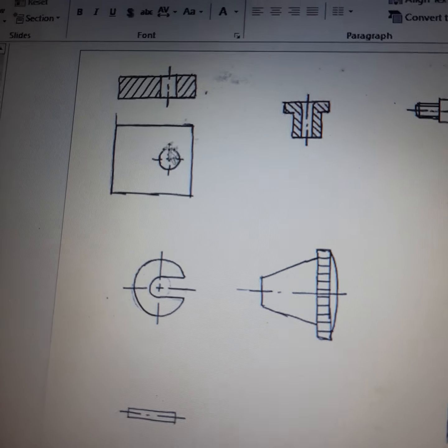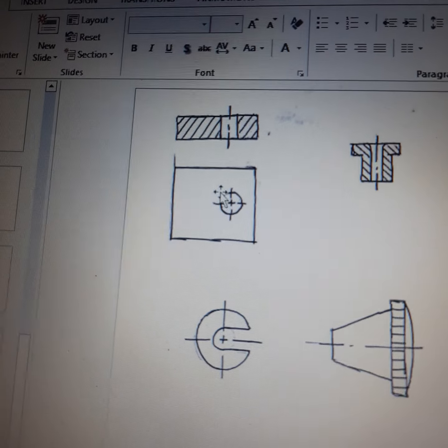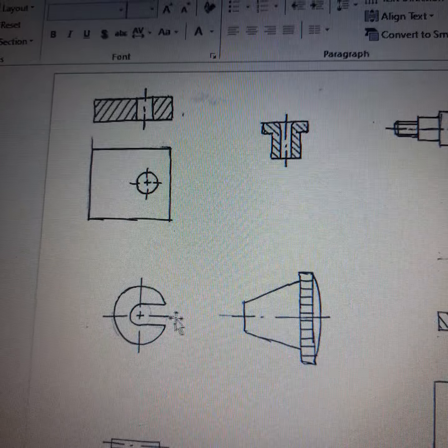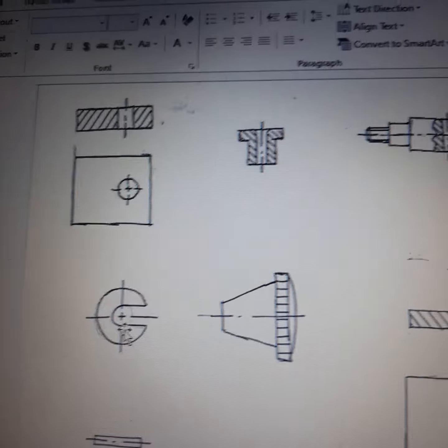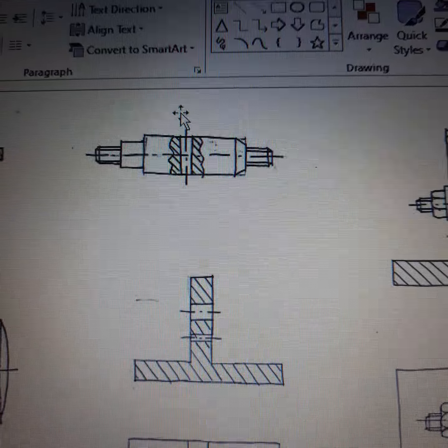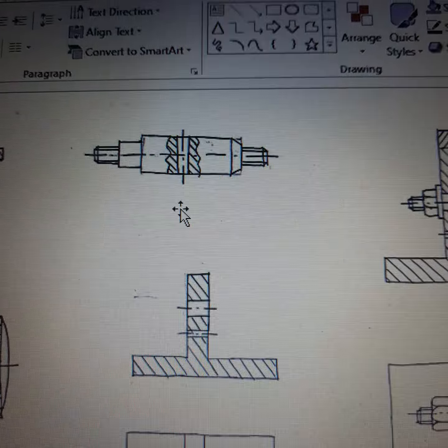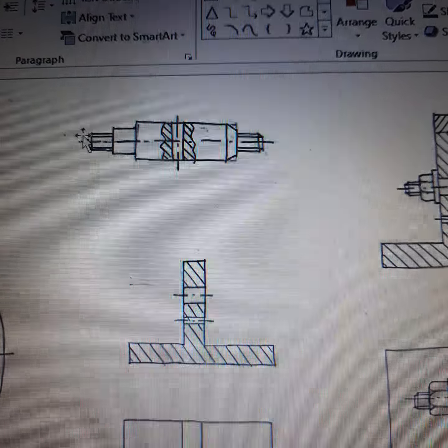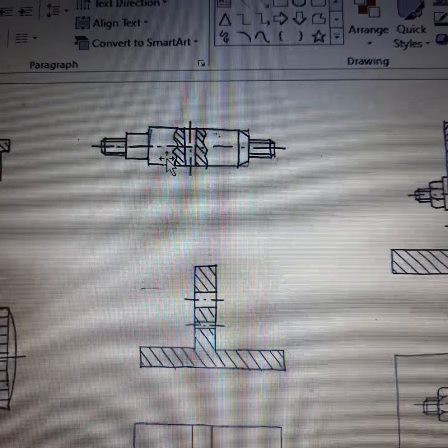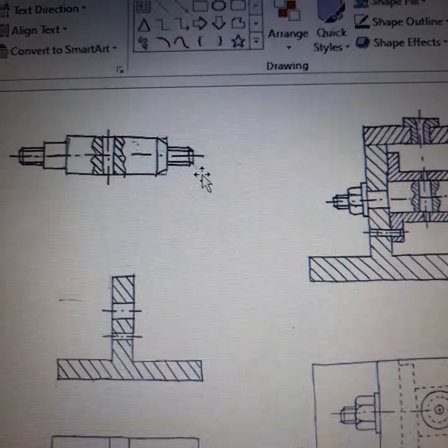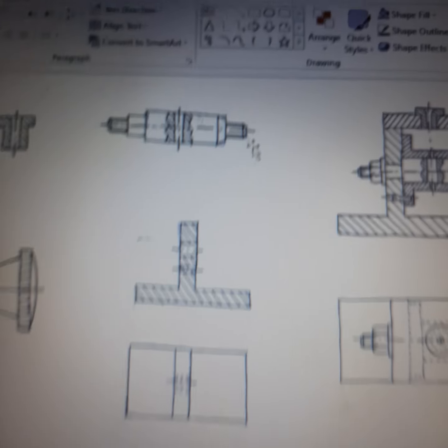So this is the drill plate. We have a hole onto which the drill bush is to be fitted. This is the C washer which is used to clamp the workpiece along with the hand nut. This is the hand nut, and the location post drawing is shown here. We have a hole already drilled, as already discussed. This set of the location post is used to fit it over to the vertical leg of the base, and on this end we have a thread for clamping the workpiece using a C washer and hand nut.